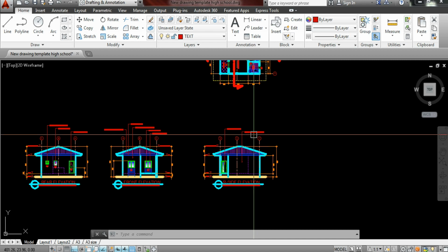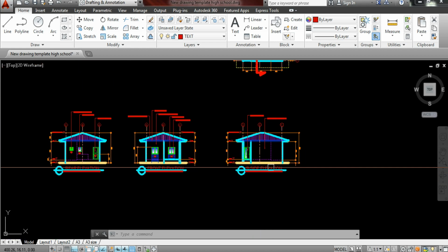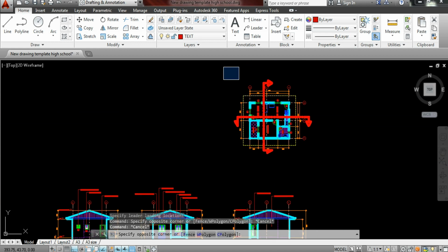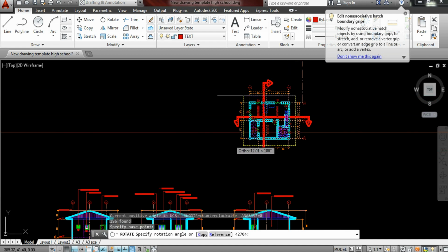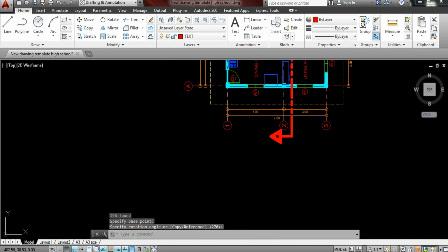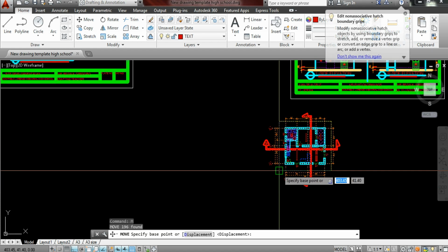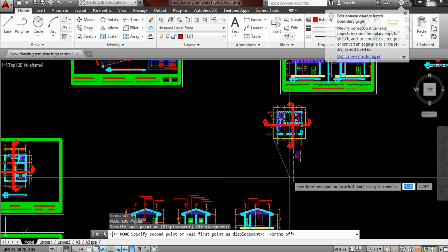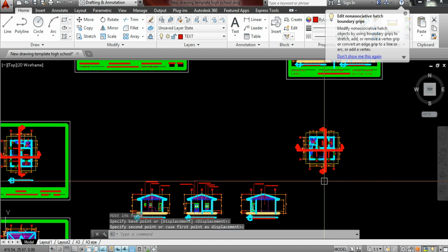Okay. So, the only thing that we have here right now is what we call the left side elevation. Because we already have the rear elevation, what I will do is simply rotate it. Okay, highlight and then rotate. And then, we already have our left side elevation. So, move the drawing into your most desired space. I'm going to turn off the F8. I'll put it here. Okay? If you wish to move a little bit further, you may do so.